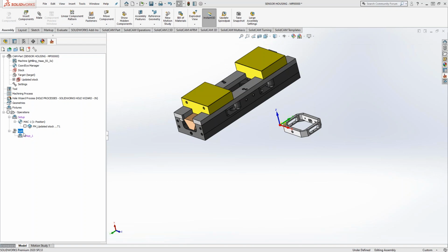That way I don't have to worry about accidentally posting stuff from side 2 while I'm posting side 1. You can let the software just figure that out for you by leaving that split in there. And with a lot of the newer post processors, if you don't have that split in there, it should still come out in 2 different G codes. But if it doesn't, like I said, this is more post processor dependent.